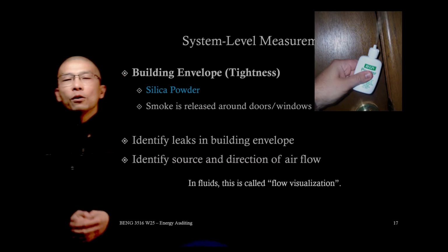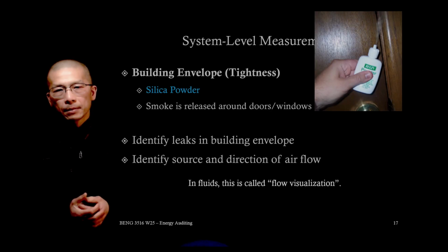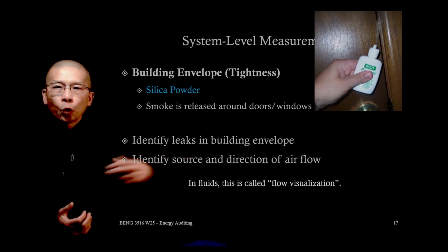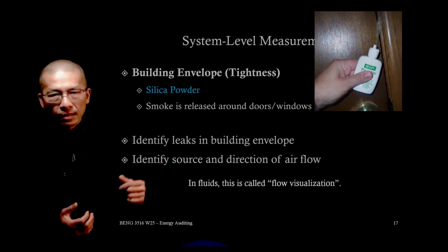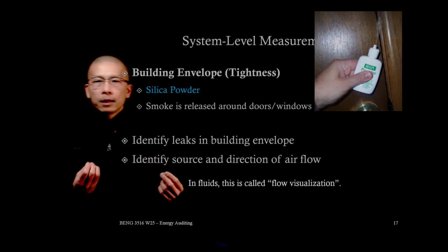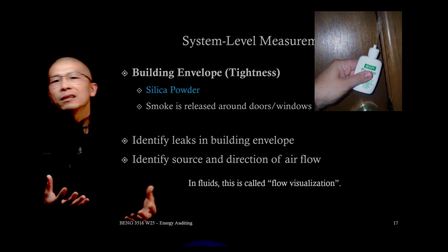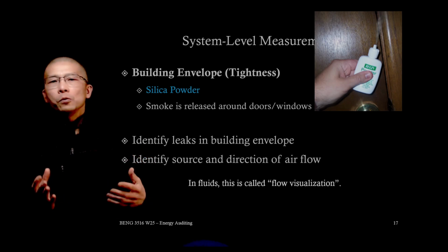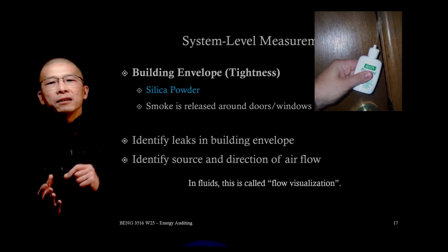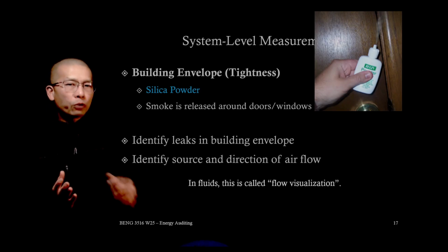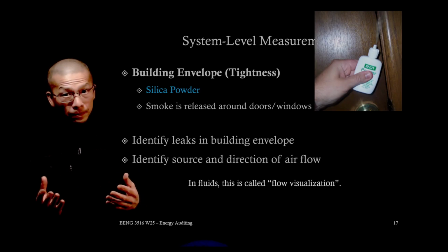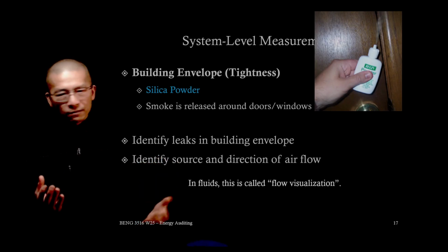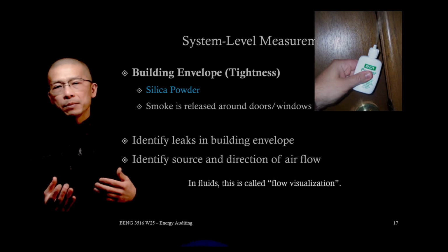Okay. For system level measurement, one thing we can do is to set up pressure differentials for the indoor-outdoor environment. We are asking how leaky the whole building is as a system, right? To answer that, we need a driving force. In buildings, air does not move reliably without a driving force, which depends on pressure difference. Sometimes there are natural drivers, wind, stack effect, but they are uncontrolled and can be variable, right?